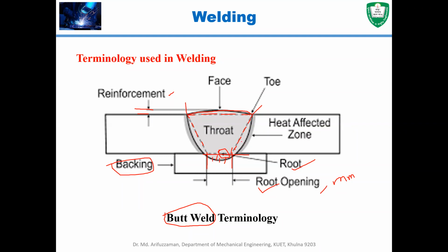Since this location is subjected to a very high temperature, that will affect the base metals too. That means some of the base metal will melt. If you look at this location, this is the initial location and this is the final location after welding. So this metal actually melted. This molten material, after reaching room temperature, gets solidified.